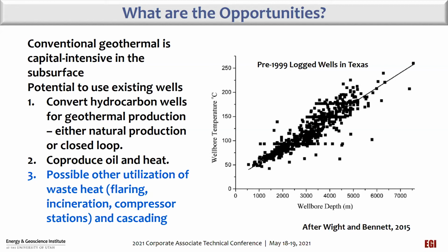Conventional rule of thumb might be that a standard organic Rankine cycle plant can easily operate at 150 degrees centigrade. But what we have found with newer developing technologies is that these technologies, with improved conversion systems and improved refrigerants being used in these systems, can produce electricity where the wellhead temperature is much less than that, and in fact less than 100 degrees centigrade. With some loss in efficiency, but the utility of these systems is improving as we speak.